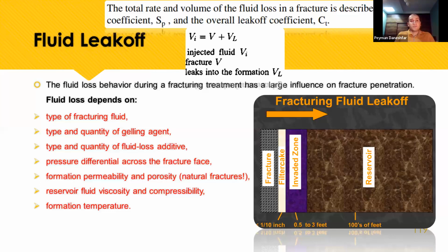The fluid loss behavior during a fracture has a large influence on fracture penetration. Fluid loss depends on some parameters: the fracture fluid, quantity of gelling agents, quantity of fluid loss additive, pressure differential across the fracture area, formation permeability and porosity, reservoir fluid viscosity and compressibility, and formation temperature.